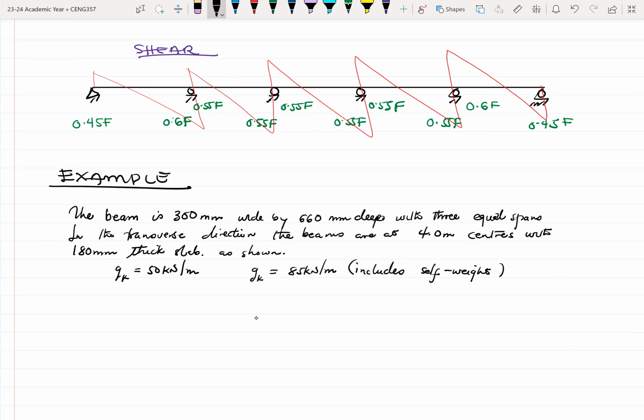Okay, great. So our FCU is 30 newtons per millimeter squared, and then Fy is 460 newtons per millimeter squared. Let's say our FYV. Since we've not watched the video, some of these terms will look a bit strange to us, but that is fine. After you watch, everything will come full circle to you, right?